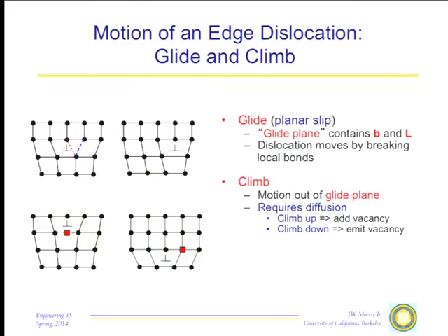And dislocations in most materials are fairly easy to move. That's why many materials, metals for example, are ductile and fairly easily deformed. There is, however, a caveat on that, which raises the question: why is the slip that we see so planar? Why do the lines seem so straight? There's a very good reason for that.